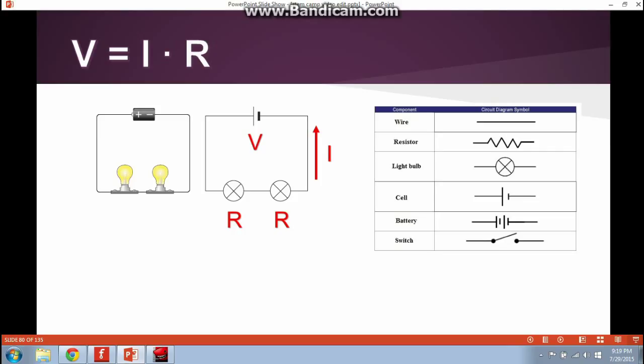we force electrons to flow through resistances, and most of the time we make them do work for us, such as lighting up a light bulb. And as the equation implies, the current and resistance are inversely related. So if you have a greater resistance and a fixed voltage, then the current flowing through your circuit is going to be lower. And we'll go over that when we touch on voltage dividers again. It'll make a little bit more sense.